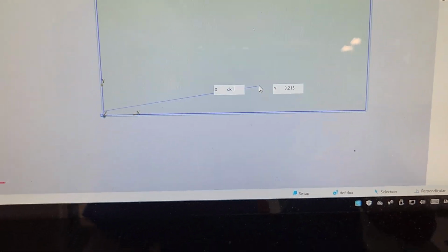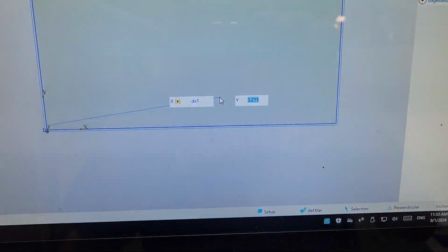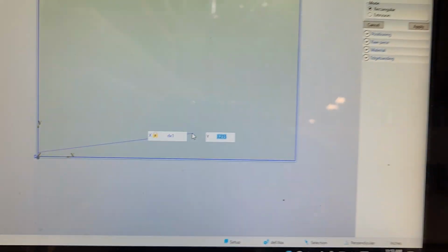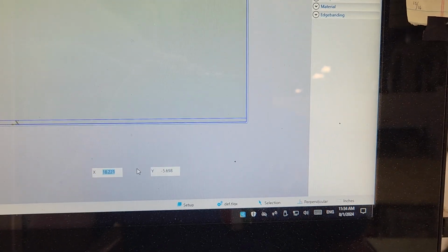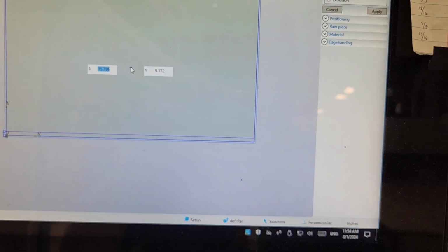And then to cycle to the next coordinate, you hit tab, and now you can type in where you want the y coordinate to be at the other end of this line. So I'll do 0.5. Click enter, and now we have that line. And it keeps me on the line function, so I could do 100 more lines.